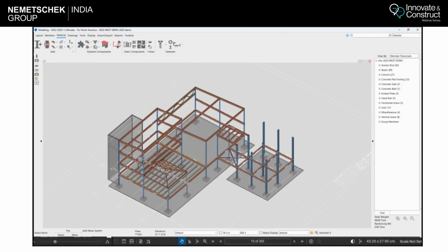Okay, you can add your assemblies or any plugins like your safety holes or nailer holes from here. You can reinforce the bottom end of the column or beam, like your base plate or any stiffeners for web penetration or column stiffeners you can add. This is for adding your thickened slab and those kind of things. This is for adding a cap plate or shear key or shims under a beam. This is for adding a post stop. This is for adding in a bolt stud or weld.